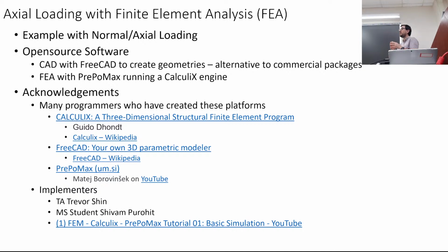Finite element is saying we're going to break it up into a number of discrete elements that we can then use to approximate the behavior of the overall object. So you have to choose a sufficient number of blocks in order to make this work.